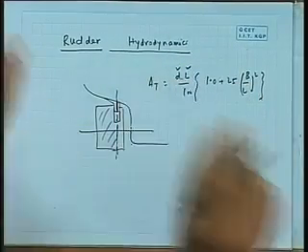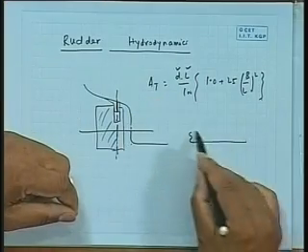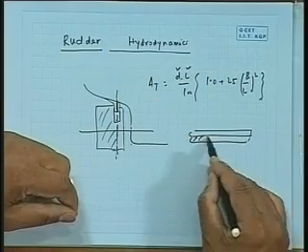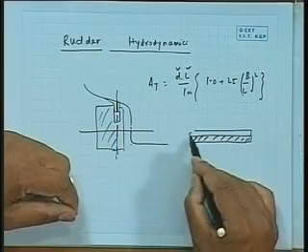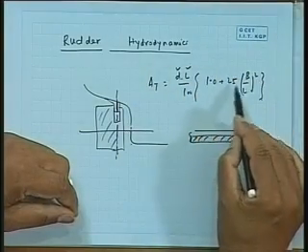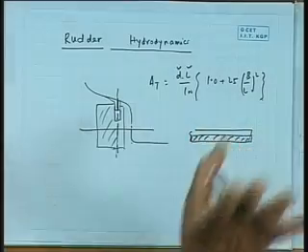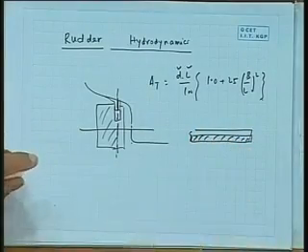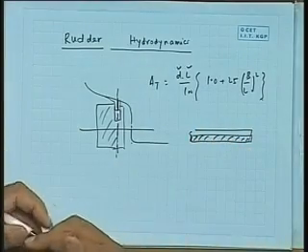That d L is, for a ship, the center plane area, more or less this area. So A_R is some kind of percentage of that. As I say, if you work it out, this will turn out to be again around 1 or 2% or so. The purpose of today's talk is how rudder produces force, how the cross section looks like, and some detail regarding its performance.